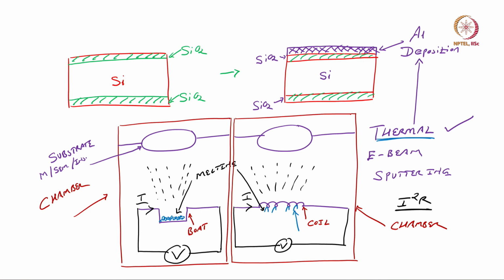So, going back to the schematic, this is a substrate holder. Now, let us load the substrate. For us, you have seen silicon in one of the lectures. I will load silicon wafer. So, one silicon wafer and second silicon wafer, here also one and second, and then we connect a pin so that it will not fall. So, this is our silicon wafer.